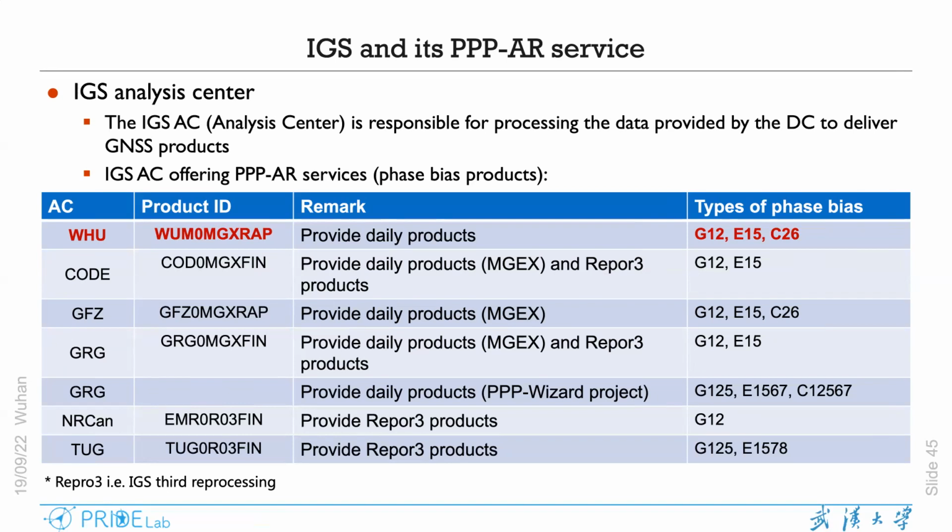This will take care of the different coordinate systems and different time systems. In the clock file provided by the IGS, the clock file also contains all of the constellations, so you don't need to worry about the time system difference. All of the time datums have been aligned with the GPS timescale. So after you have your positions available, that position is with respect to the GPS timescale.